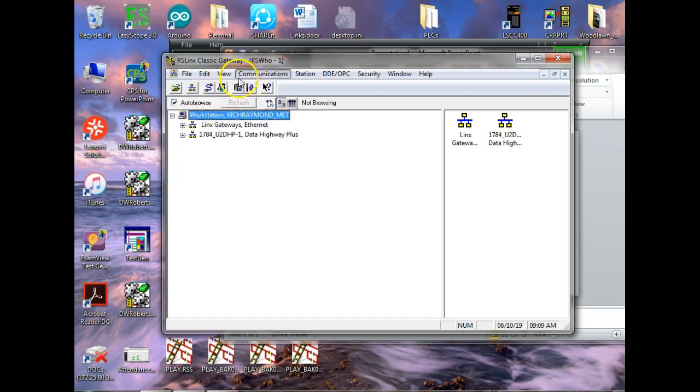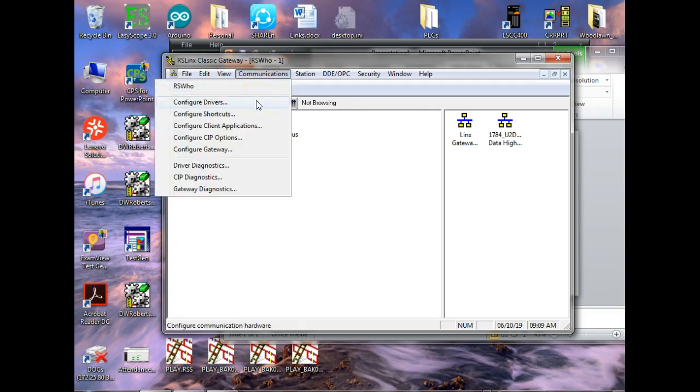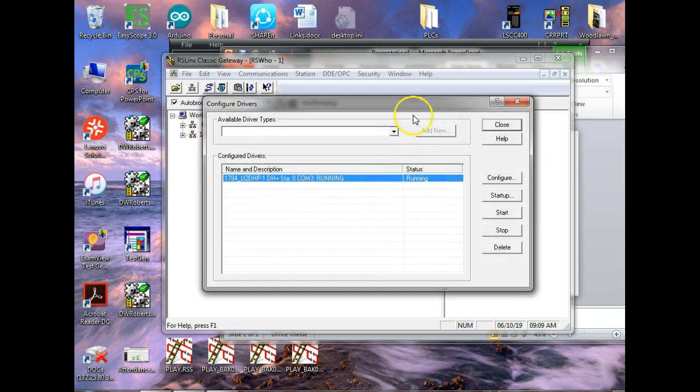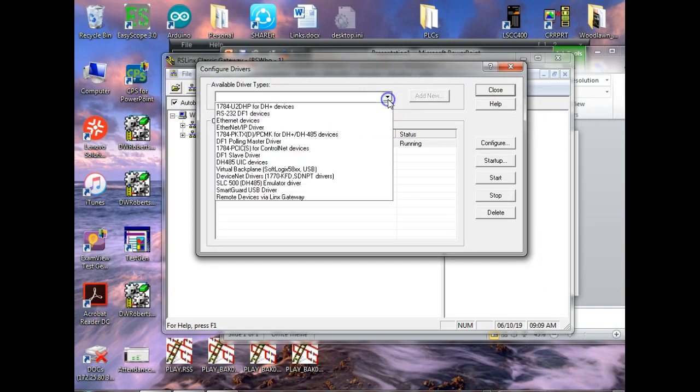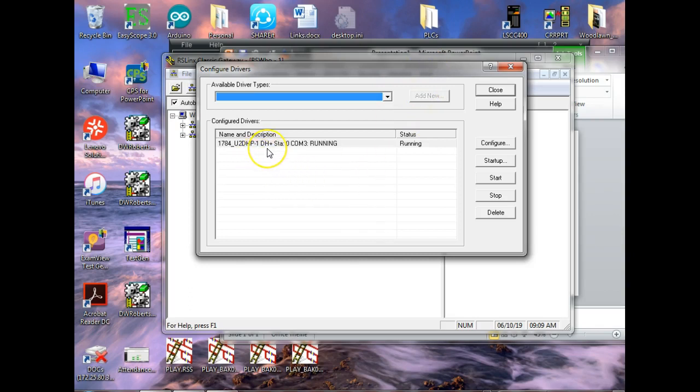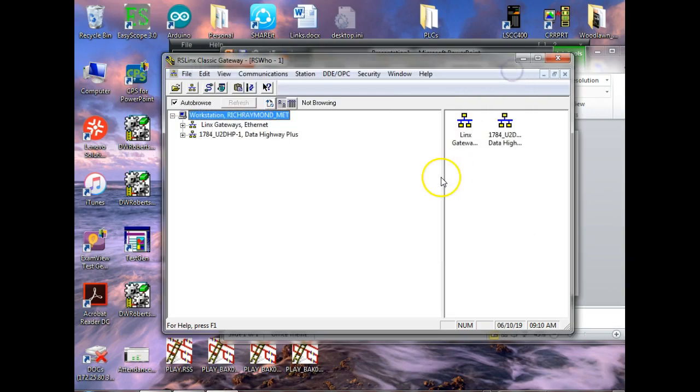And this is where, so what's a driver? Yeah, it's a piece of software specifically designed to run a peripheral, a device. And of course, this is all the drivers this guy here supports as far as communicating with other PLCs, other CPUs. We're using one called DH485, which is called the data highway, and it's already running. So that would be the first thing I would do.